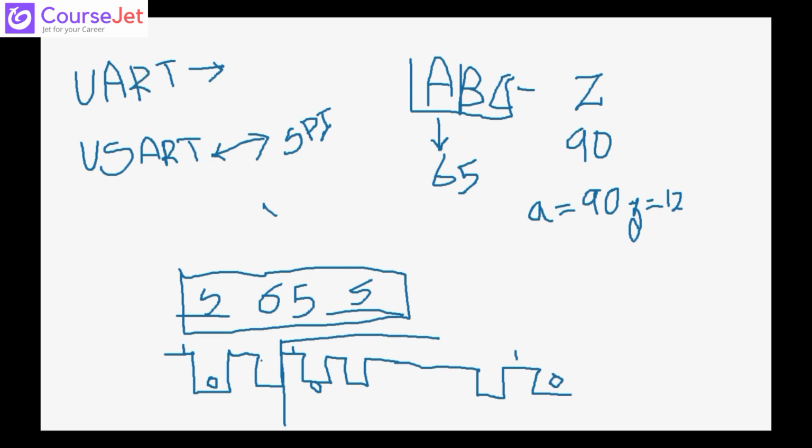The only thing that changes is how it sends the start and stop bit, how we need to select it, and how many wires or which mode it is using. The basic operation of your UART peripheral is the same. Once you get this, it is the same anywhere. Only the pins, the naming and the registers change, but the basics remain the same.